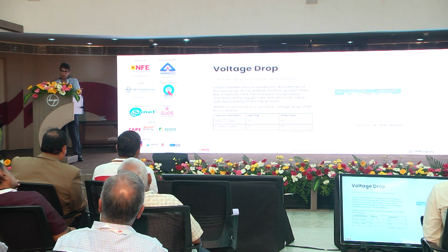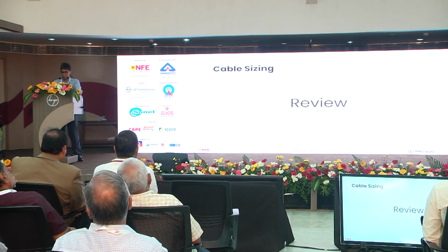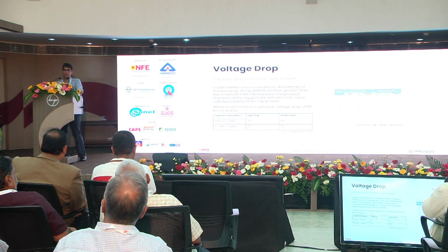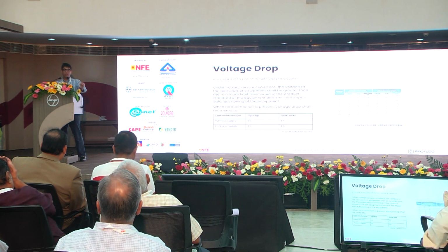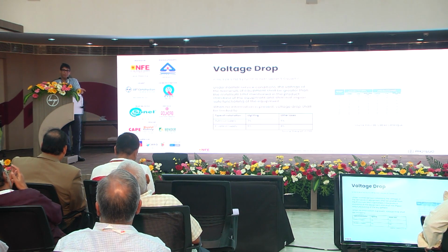Remember, for 3-phase loads, the voltage drop is different. You have to do 400 or 415 volts times 3% or 5%. See, in a public supply, if you notice, the transformers are actually rated for 433 volts at the output. In a private supply, you might not have that. It might be putting out 415 or such, which is why you make a greater allowance for voltage drop in a three-phase system.